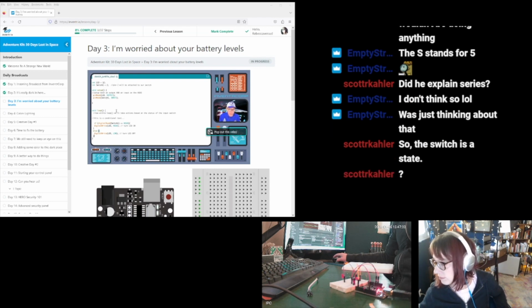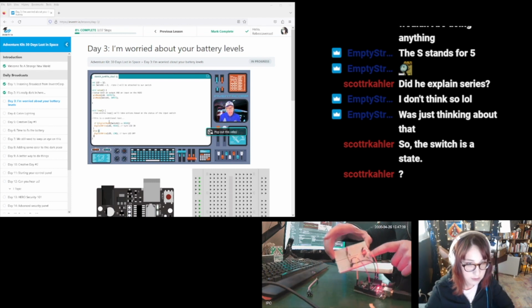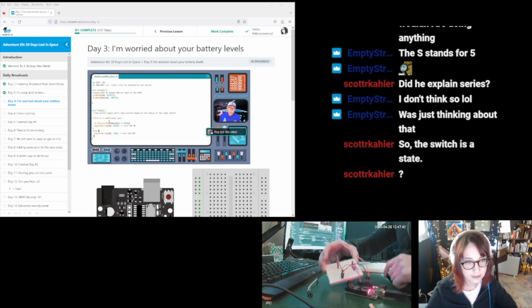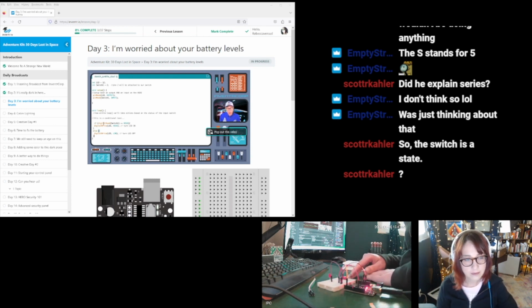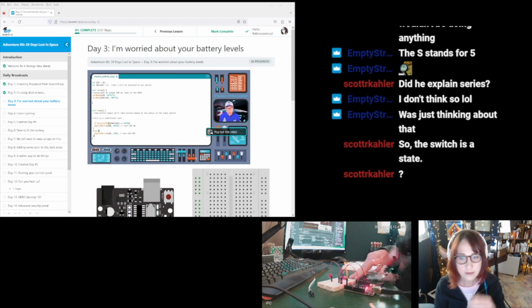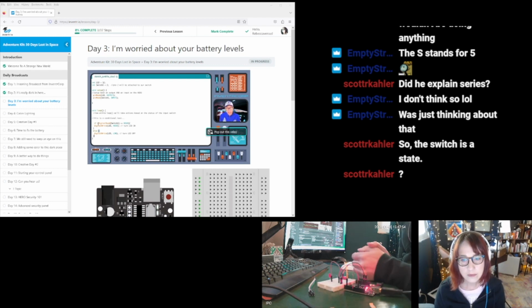Now, the next thing that happens in loop is something new. We're going to apply a conditional test. We're going to ask the Hero to check what is the voltage on pin 2, or in other words, switch 1. If digital read of that switch of pin 2 is equal to high, then take the action contained within these curly brackets, which is our usual action of turning on the LED on pin 12. So in other words, set LED to high, so the light will go on.